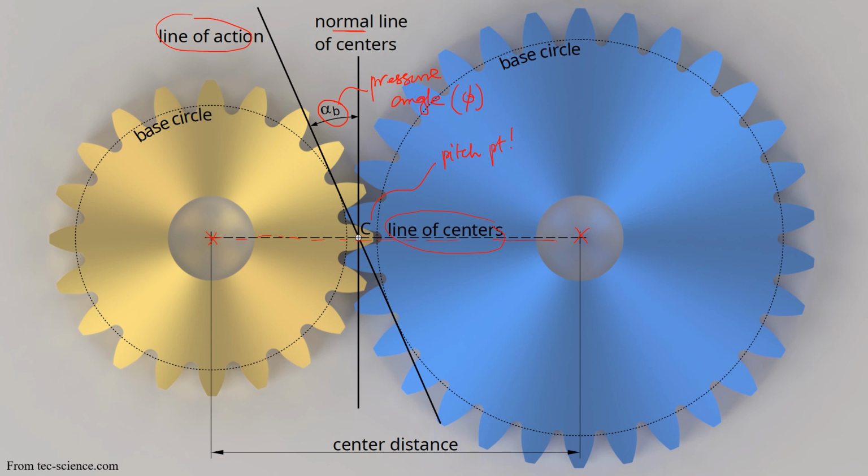This pressure angle is an important parameter because it defines the effectiveness of torque transmission from one side to the other, and the standardization and the number of teeth all correspond to the pressure angle specification. At this stage, you can see that we are gradually incorporating the necessary terminologies on the diagram so that you can understand how to construct and realize them.